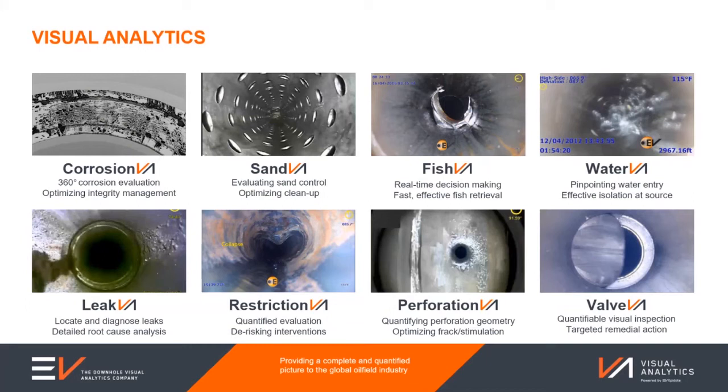But alternatively, with the array camera, we could position that above the production logging string, looking at the 360-degree images and allowing the production log to work in full underneath, undisturbed. So I hope that answers some of it. But if it comes to it, we could do a separate run altogether. We do this sometimes with well integrity surveys. If you've already run a production log or, let's say, a multi-finger caliper survey, we could then come and supplement that with a secondary video log and help combine those two data sets together retrospectively. So either or, but certainly in the same run means you're absolutely comparing like for like under the same conditions.